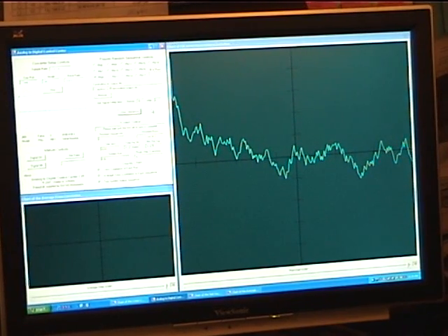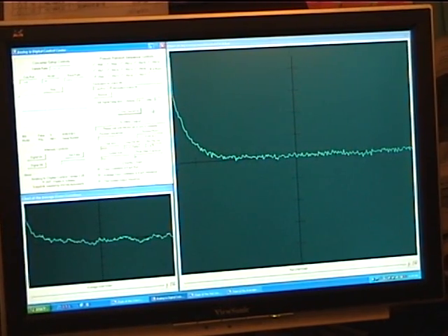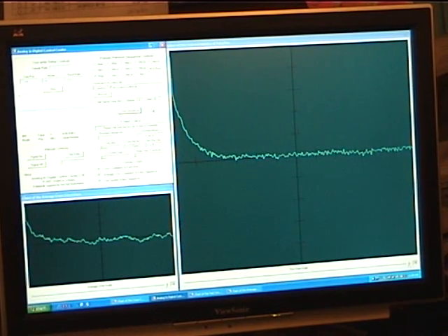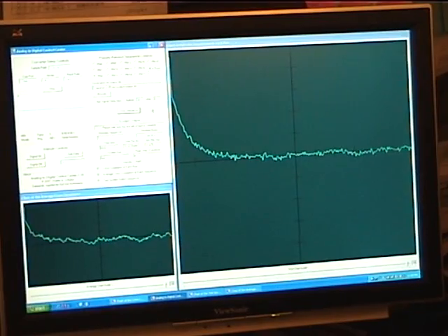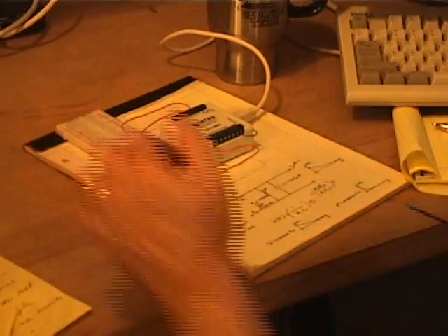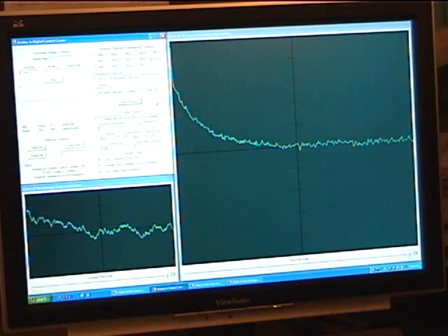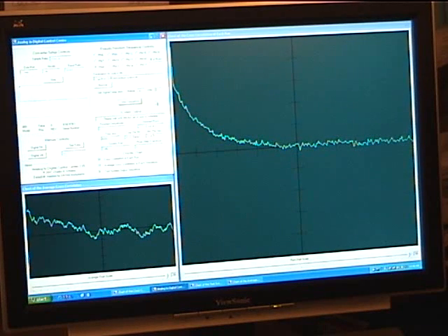You will notice that the cross-correlation method requires one complete pseudo-random sequence to be injected into the test system before the calculated impulse response waveform will be accurate. This requirement is easily verified by reviewing the calculus involved in the cross-correlation theory. After adjusting the trim pot on R2, the expected longer settling time of the impulse response is displayed.